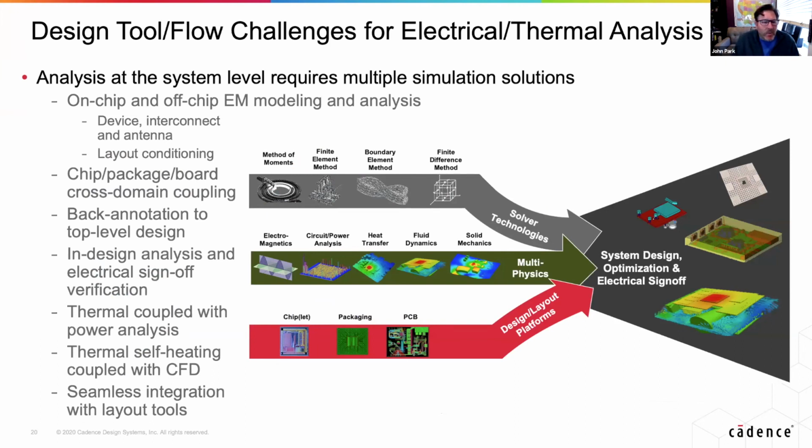So here again, the world of EM extraction comes in. If you're an SoC designer, you mostly use tools that just do RC extraction, kind of a table-based way of looking at layout parasitics. When you move to the system world and off of the chip and into interposers and packages, you need more advanced electromagnetics tools, and you need in-design and sign-off level tools.